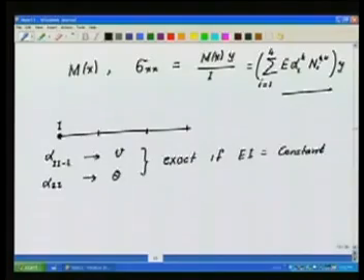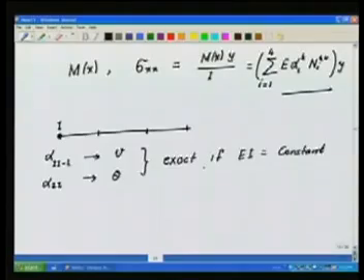So, for constant flexural rigidity, the nodal values of the displacements, that is the alphas that we have obtained, correspond to the transverse displacement and the slope at this point, and they turn out to be exact provided EI is constant. If EI is not constant but it is smooth, then the nodal values are very good but not exact.